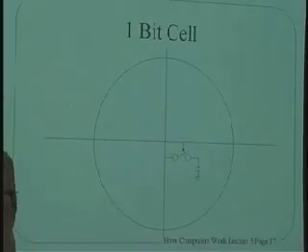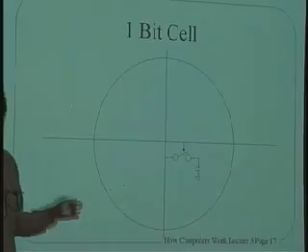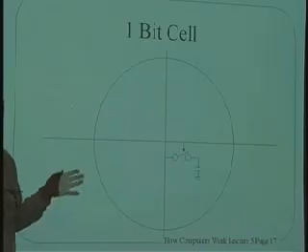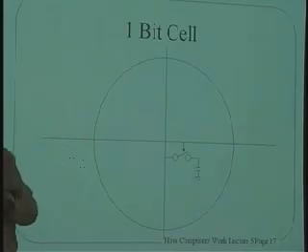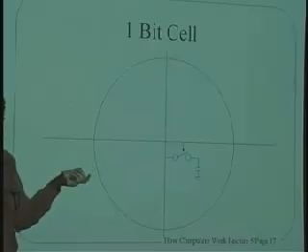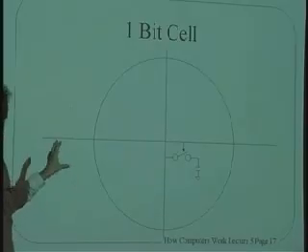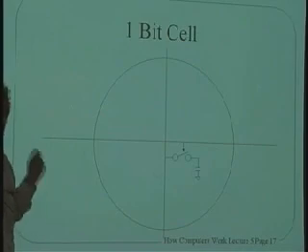But if too much time has passed, you're dead. Okay? And that's the reason that if I suddenly disconnect the power from my laptop and hook the power back up, the laptop doesn't come back to life exactly where it left off, unless I write a bunch of special software to take everything in the memory and write it out to non-volatile storage, which is the disk, which stores things a totally different way. I can't trust the DRAM, the dynamic RAM, in the machine to hold on to this charge. And in fact, this is called DRAM, the D of dynamic random access memory. The D means that it is dynamic, meaning that I cannot depend on it statically to hold charge.